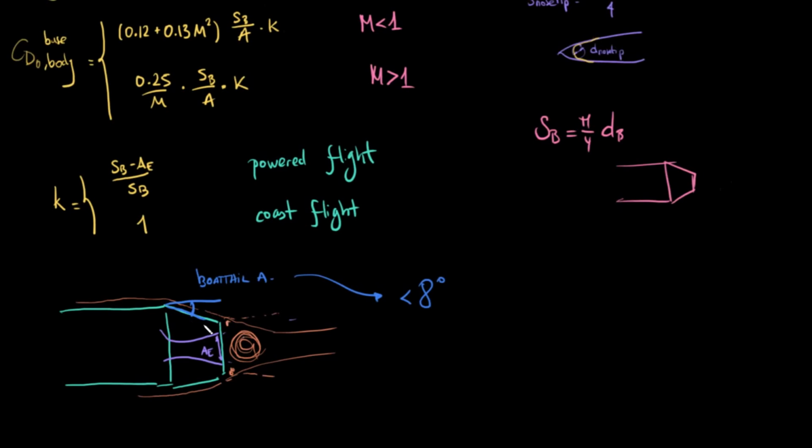So if you want the flow to stick to the boat tail, you gotta choose really low angles, like 6, 8, 10 at most. If not, you're gonna get an even worse effect than what you were trying to get in the first place with the boat tail. So yeah, that's a rule of thumb Fleeman suggests.